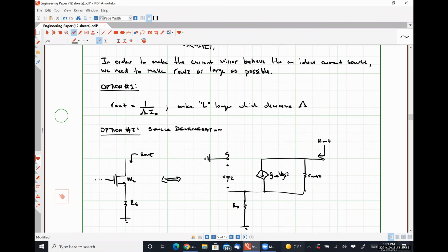How can I do it? Any of you guys remember? So I'll give you a hint. We're looking in, and the network that we have contains a dependent source, but no independent sources. So go back to your circuits 1. What did we do? Superposition requires us to have multiple sources, and we currently have 0. Test source method, right? We just want the Thevenin resistance to this dumb thing.